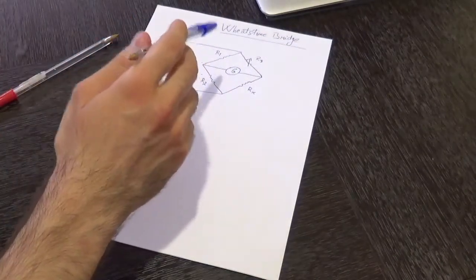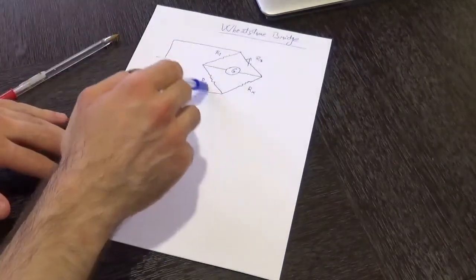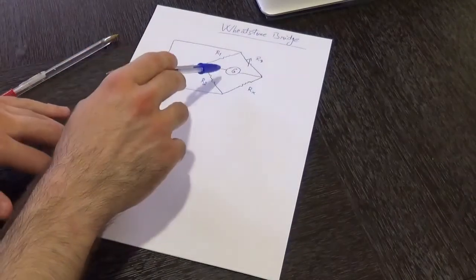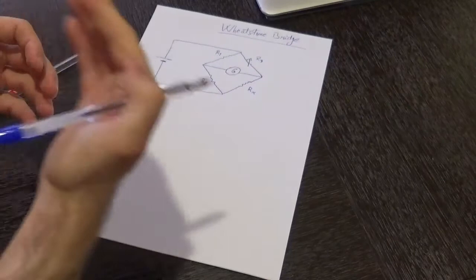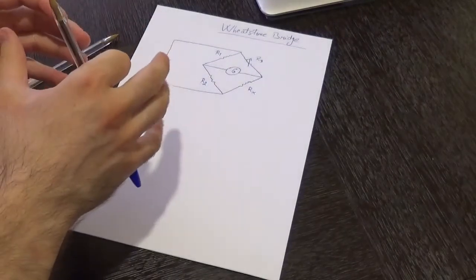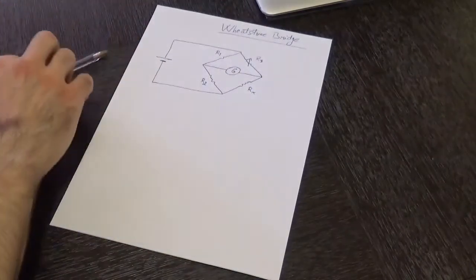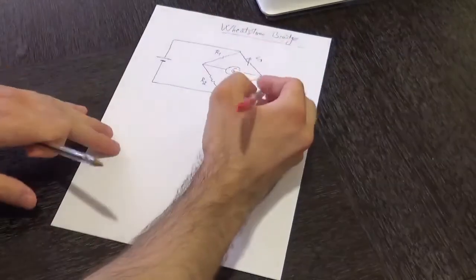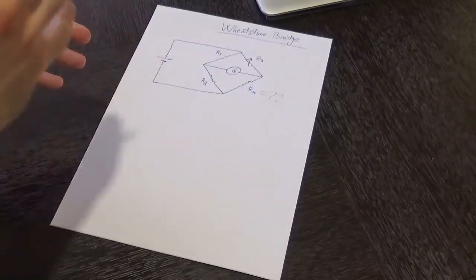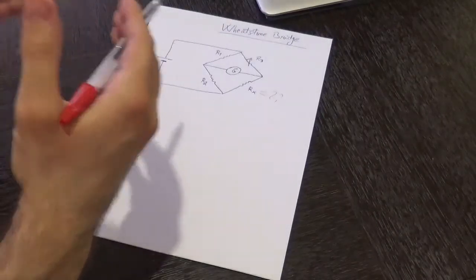That galvanometer is basically a voltmeter that is going to be measuring the voltage difference between that branch and the other one. And over here we have a power source supplying that circuit with a voltage, with a potential difference. Now the Wheatstone Bridge is used in order to measure the value of an unknown resistor. So the target of that Wheatstone Bridge is basically to measure the value of that unknown resistor Rx. And the Wheatstone Bridge works by balancing out two parts of a bridge circuit.